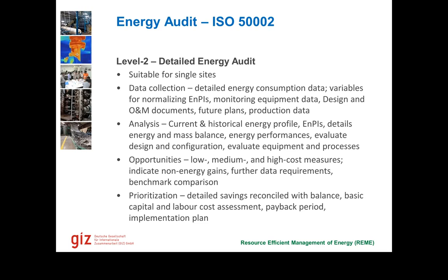Then the analysis is conducted based on current and historical energy profiles, performance indicators, detailed energy and mass balance is conducted, and energy performance is evaluated in very detail. Designing configuration of the machinery, of the equipment, of the facilities is evaluated. And then opportunities can be low cost, medium term, and high cost measures as well.